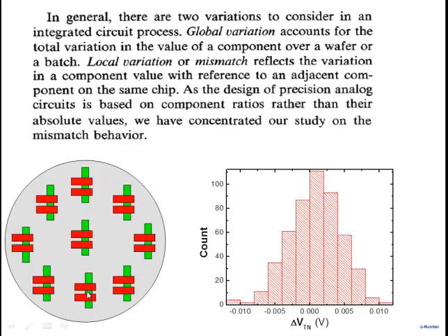So the point is that two transistors fabricated close to each other will in general have a threshold voltage difference. They will also have a difference in, for example, mobility. So the beta parameter, the K and W by L, will also vary. So there are two major effects. One is VT, which will vary, and the other is beta of a transistor. The Kn, as all of you know, depends on mobility, and mobility would also vary as you go from one side to the other.